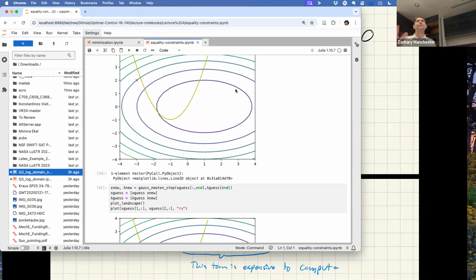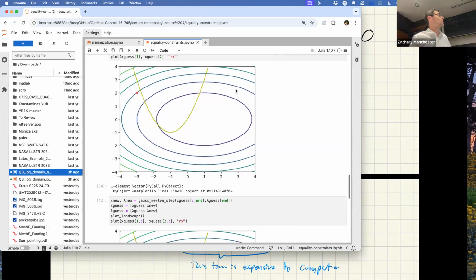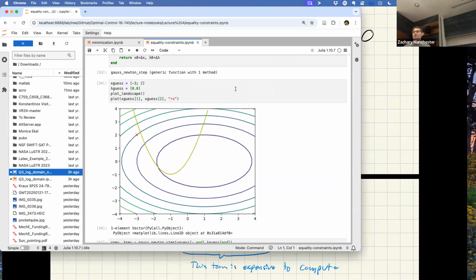Yeah, pretty much. And that's often the case in control problems. We make up the cost function, right? So if we're being reasonable, we'll make up a nice benign quadratic or convex cost function. So f is usually nice because we get to pick it. But the constraints we don't get to pick. They're usually the dynamics, the physics, safety. Those are things we're stuck with. So often the costs are nice and the constraints are the nasty part. In that case, that constraint curvature term can be bad and mess with you. That's another reason why we often use Gauss-Newton in control.